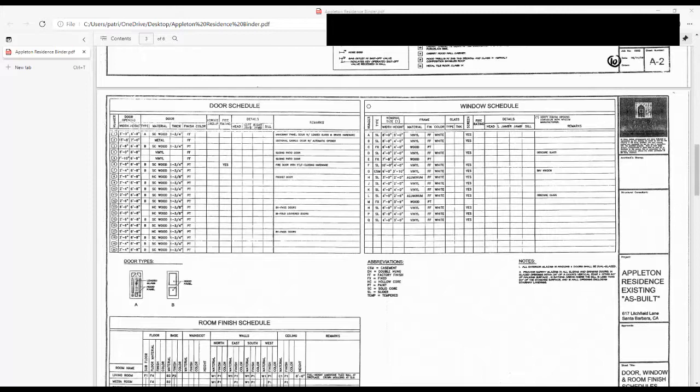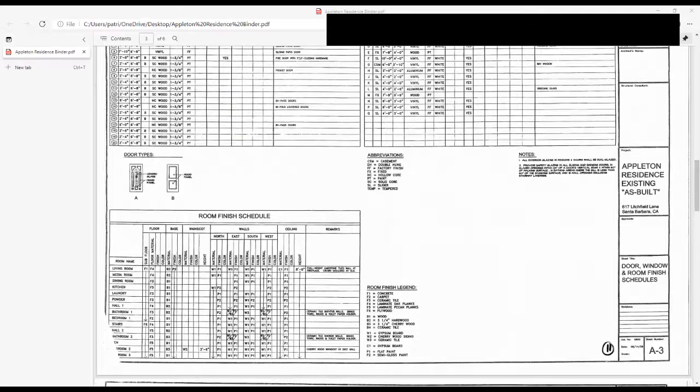But now the nominal size may not indicate the size at all. The actual size of the window or door may be bigger than that nominal size, and that would screw you up if you were framing for it. Or if it were smaller, you'd make too big of an opening and you have to fill it up. So you want to have the exact rough opening the manufacturer suggests.